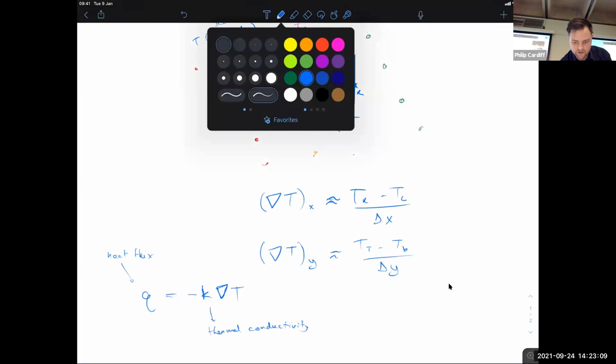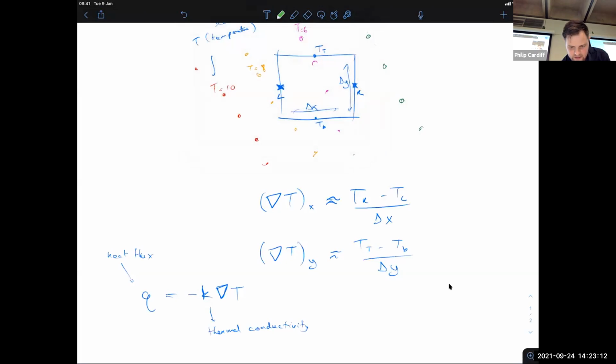So if we were to draw, pick some other color, so then maybe in this case, you might get Q flowing in that direction, that'd be your Qx, and maybe a Qy in that direction if it was hotter in that direction. Actually, based on the temperatures I've drawn, it would be in the other direction. So I said it's hot, getting colder, colder, colder. So the heat flux vector will be generally in this direction, like heat flows from hot to cold. So if I calculate the gradient here, I'll get minus numbers in the x and minus numbers in the y, because it's getting colder in the x and colder in the y. So very good. So that's this gradient operator.